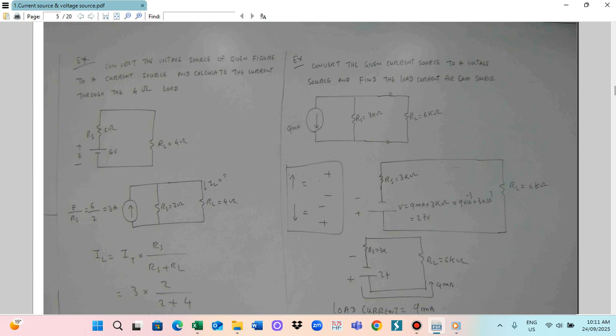So in this problem, this is the opposite of the previous one. In the previous one, a voltage source was given, so you found the current. Now the current is given, so you have to find the voltage. Today, 9 milliampere of current is passing through the resistance. So how do we find the voltage? Voltage is found by multiplying the current and the resistance.